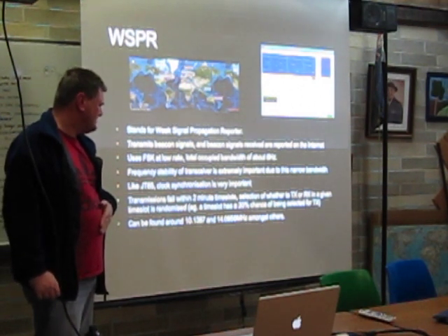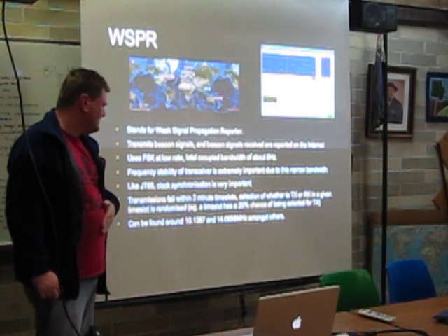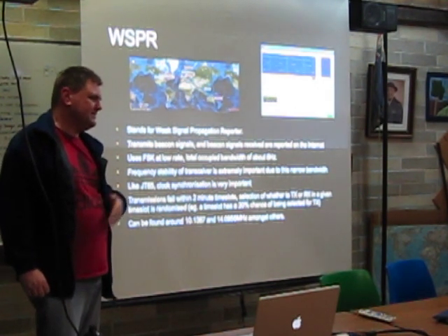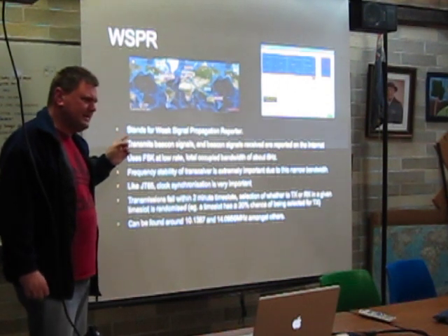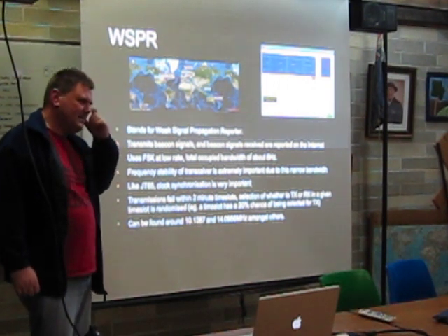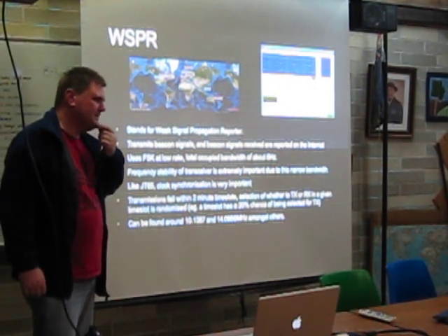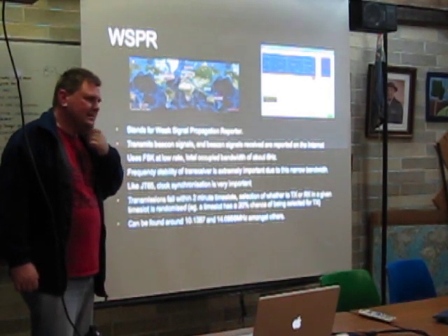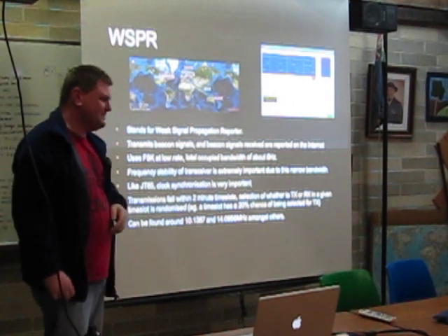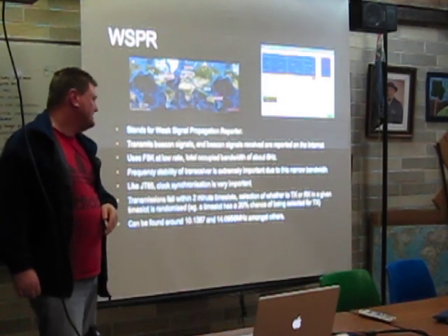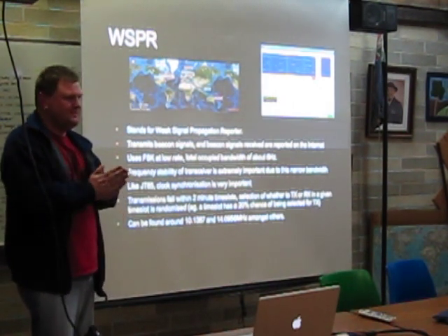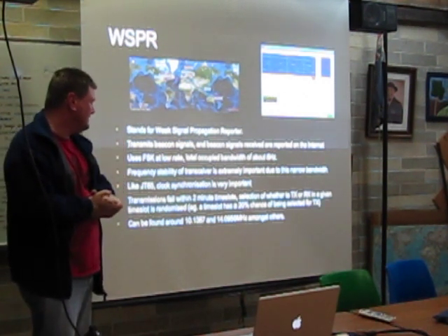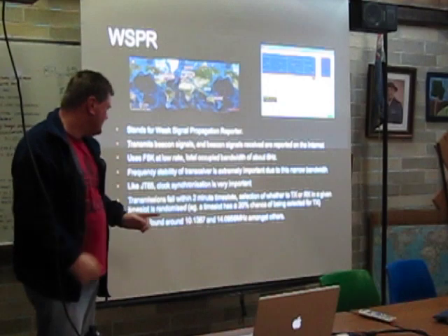This works down to about minus 28 dB signal to noise ratio. I said that for the JT65, but actually JT65 is not quite that good. I think it's maybe minus 18 rather than, yeah, this goes down to minus 28, which is phenomenal. And one of the reasons for that is because of the extreme narrow bandwidth. So you can really get a very high signal to noise ratio.